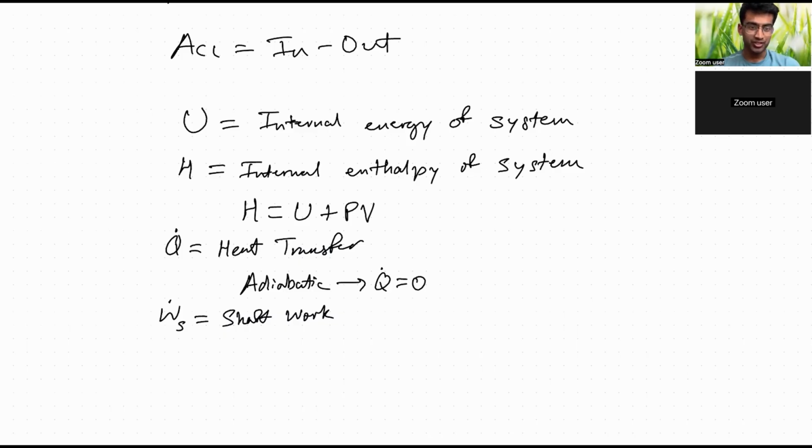Depending on which field you're in, they have different signs, whether positive or negative. If you're in physics, they have a different convention than in chemical engineering. But for chemical engineering, the important thing is if I'm doing work to the system, that is considered positive energy. I'm adding work or energy to the system, right? So, okay, you're heating something on a stove and then you're mixing it. That's a form of shaft work.